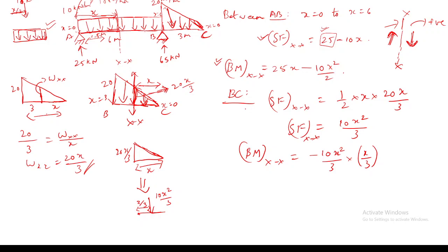Sir, here we are seeing the bending moment from the right hand side, so it will not be positive. See, you are seeing the bending moment from the right hand side, and the total load there is 10x squared by 3, and it is creating a moment like this, in the right clockwise direction.